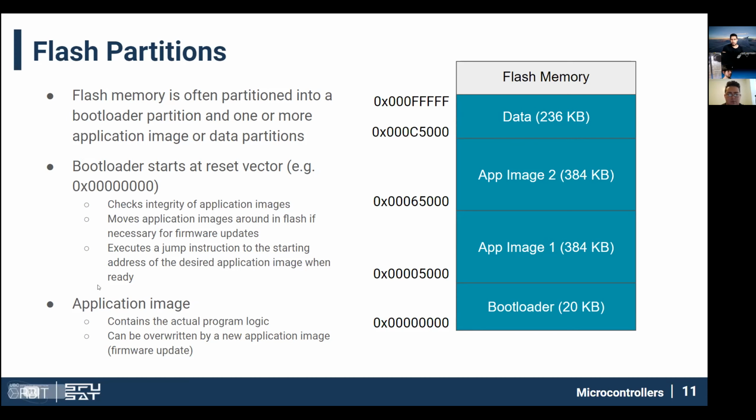Some microcontrollers also ship with a bootloader pre-programmed in. Most of these Arduino boards that you might have worked with have a bootloader already programmed in, and that bootloader can receive firmware images over that USB or UART connection. That's how you can upload code just by sending it over a USB cable. Then the bootloader writes it to flash and knows how to jump to it to start executing.